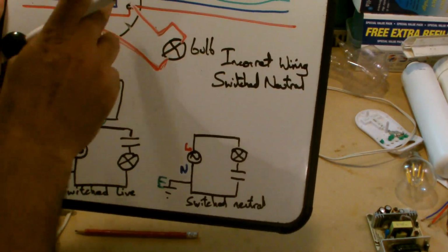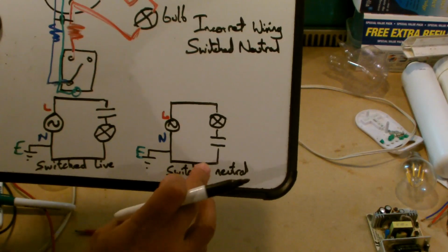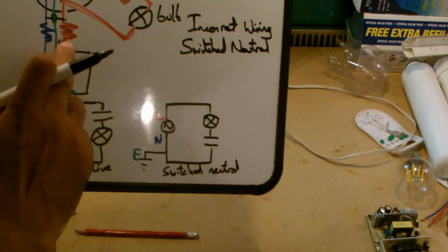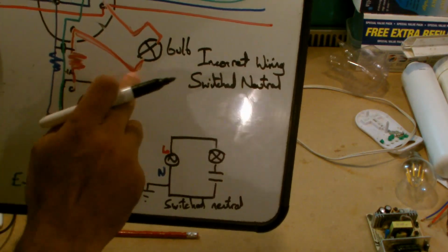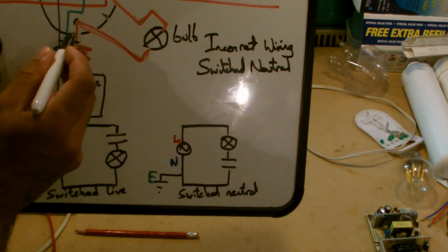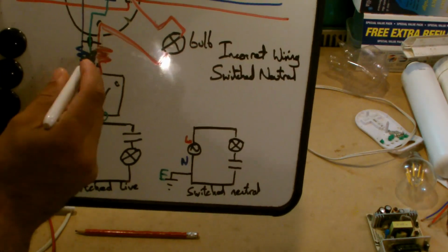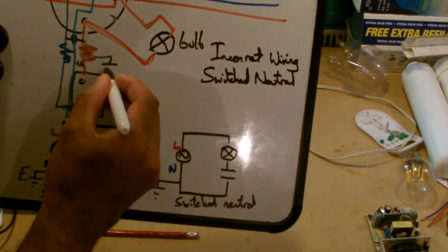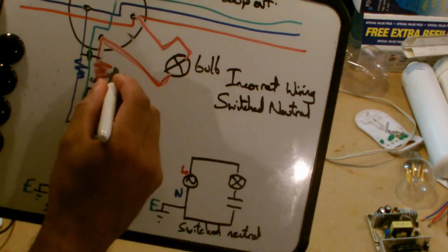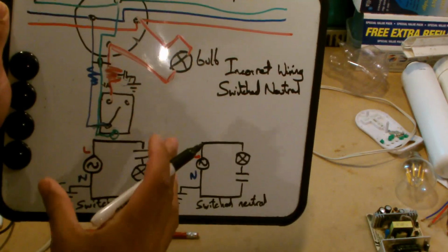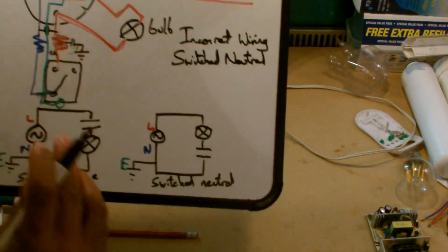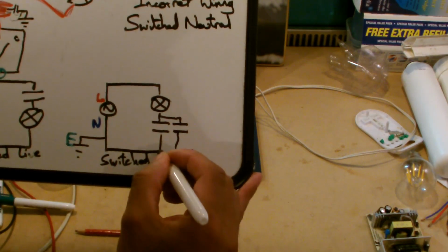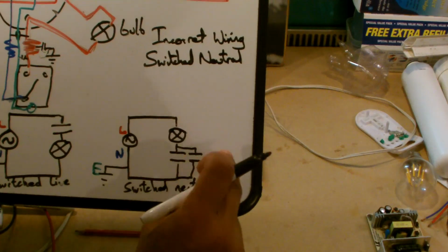So now I've drawn this earth in here. How has it actually changed the switch neutral? Well, the elements that I have here, I've got a capacitance between the cap and this floating live here. I've also got that to the neutral, which I have originally drawn in, and I also got a certain amount of it which is actually going to the outside world, which I'll draw as a capacitance to the outside environment. So all of these things add up, and effectively it's like having a capacitor in addition to that capacitor. So I've increased the capacitance.